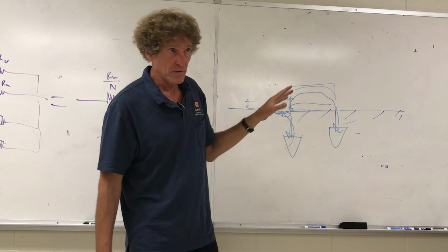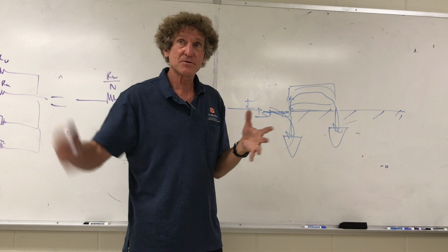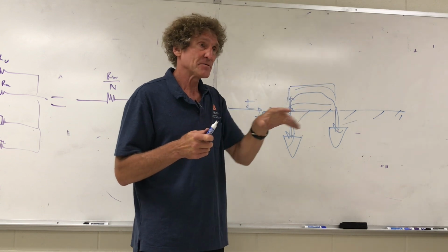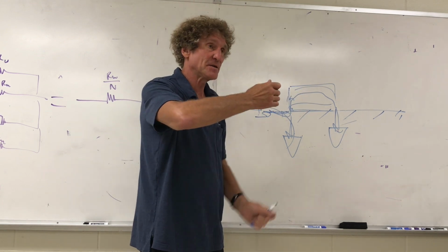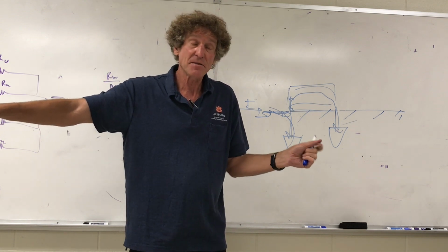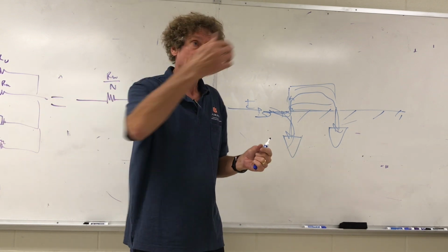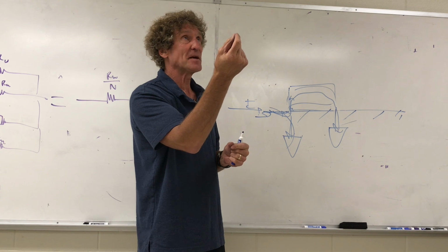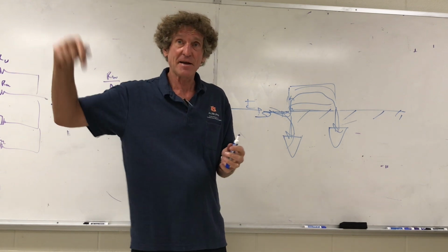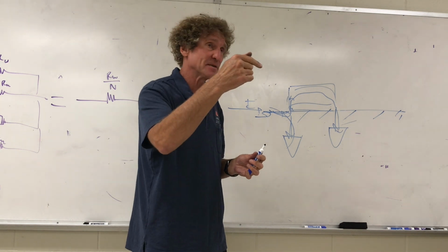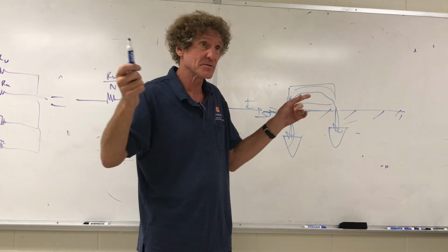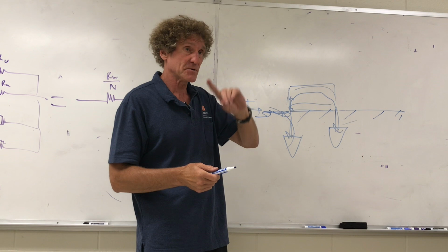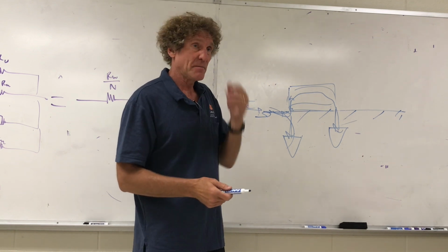It's a horrible problem when somebody just brainstorms the best way to, say, locate another extension on your house, and they put a metal frame and drive metal rods into the ground, and the grounding rod's on the other side, and they didn't think anything about it, right? And now, all of a sudden, that metal stuff is secured to something that is an electrical ground in the house. Now, lightning hits, comes across there, goes into the house, finds the path of least resistance, usually the wiring in the house, and kaboom. Your washer gets blown out because the current wants to go back to the ground in the washer, which takes it to two points now, not one, and it messes up everything.